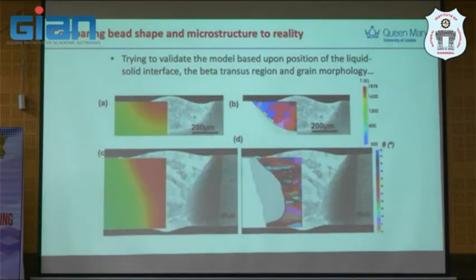So with the temperature field, the microstructure you see now is more equiaxed, and this is predicted as well. We haven't had any EBSD data. I just want to let you know this is the beta grain structure. But what you see in the experiment postmortem will be the alpha phase, because it transformed from beta to alpha, the last phase, which is similar to martensite in steel.